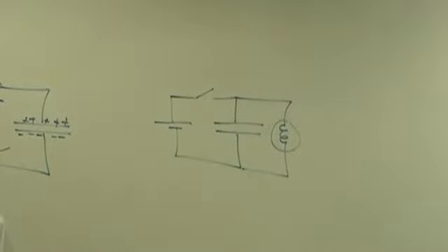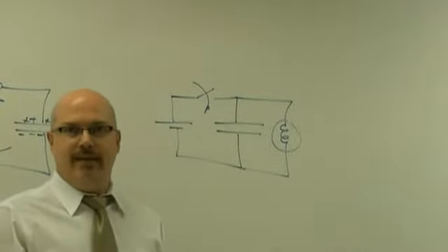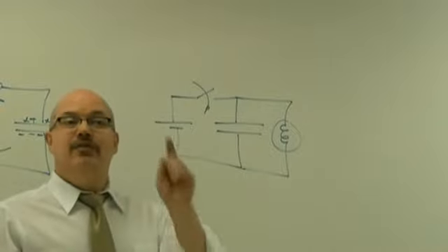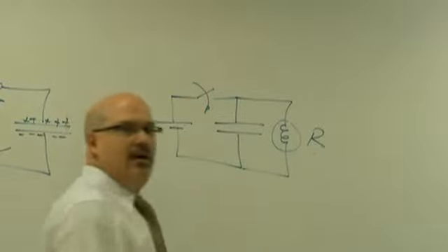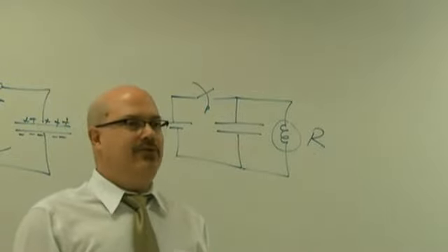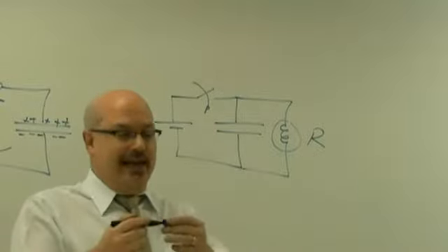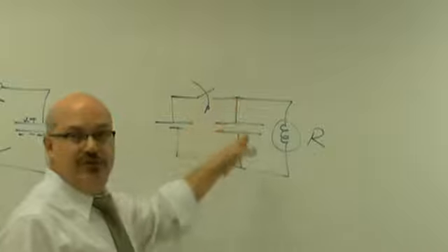Hey, now what if we do one like this? And I throw the switch. The light bulb will... At the very beginning, this thing has resistance, right? It always has. But what's the resistance of the capacitor at the very beginning? Zero, because it's got lots of room for the charge to flow on, right? So this acts like a short circuit.